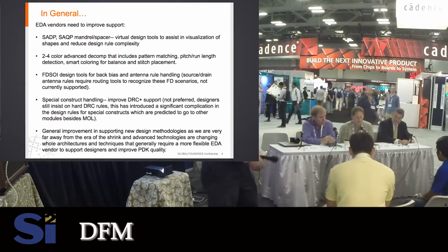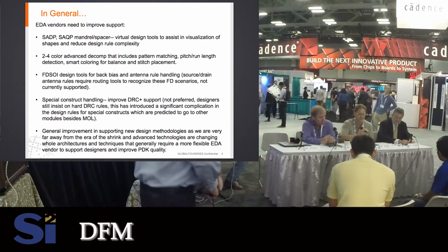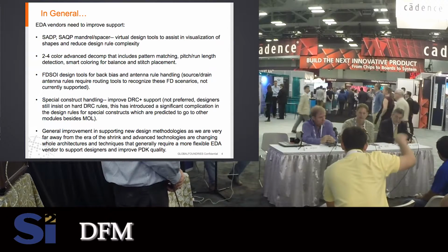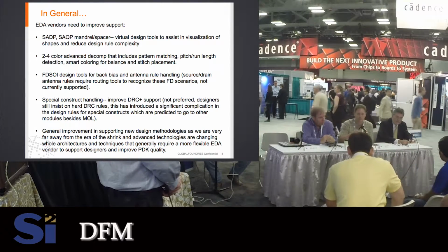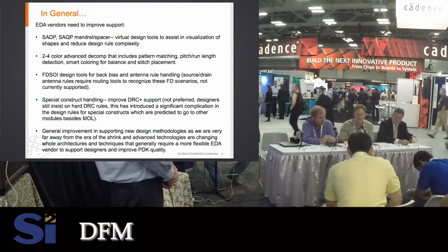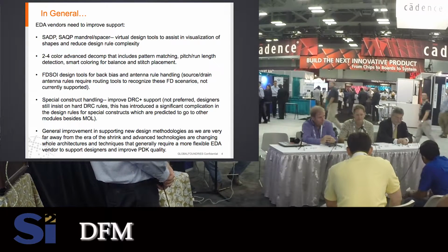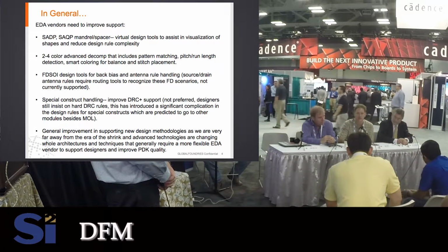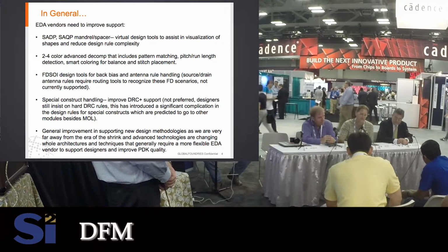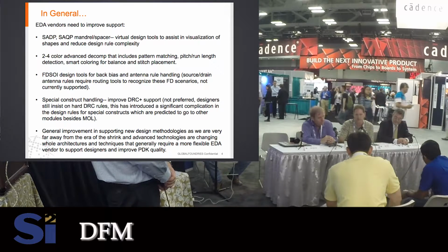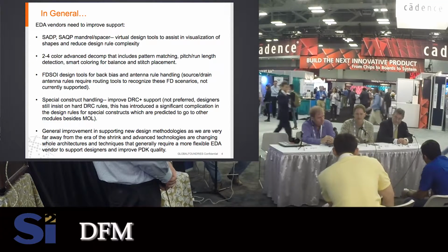So obviously you're looking at the devices themselves. Can they handle it? So the first point is your schematic, your circuit. Is it going to handle that capability? You have to be able to identify those circuit nodes that will see the elevated voltages, and identify those on the circuit so that you can simulate and verify the voltage.